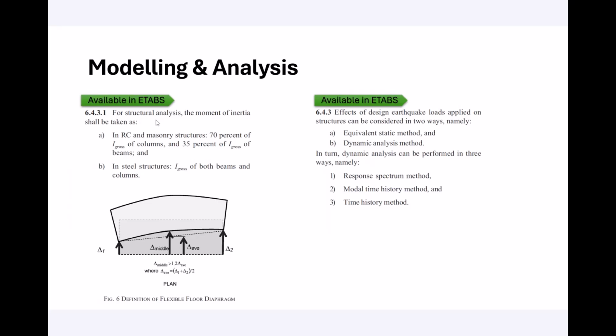All right. Now the property modifiers are available in two locations to define. One is in the frame definition itself, or the section property definition itself, for beams, columns, walls, and slabs, where you can specify the modifiers directly. The other one is selecting the objects after the modeling and applying it as an external assignment to the members.